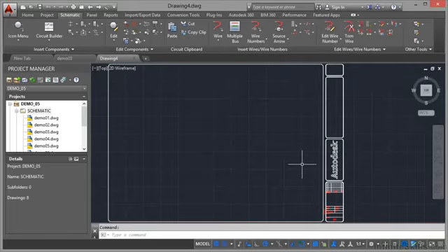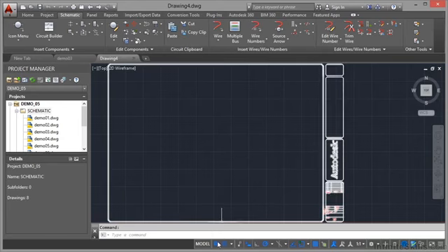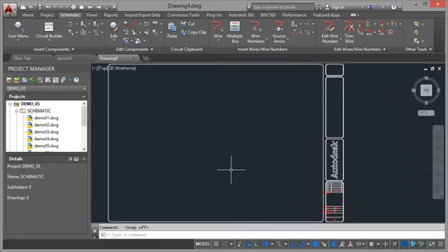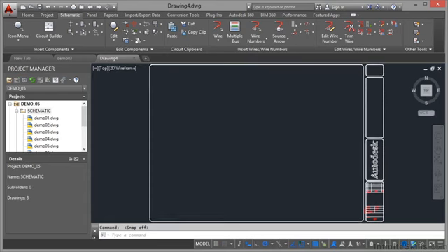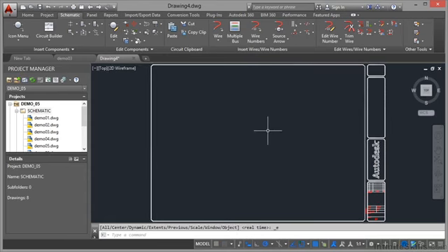Now you'll notice as soon as I do that, I get a blank new drawing. The grid is switched on. I'm just going to switch those off down here on the status bar. Grid and snap are off. Double click on the wheel to zoom extents like so. It centralizes it nicely. Now at the moment, if you look at the top of the screen, that's just a default drawing4.dwg. Now what I'm going to do is I'm going to do a save as on that.